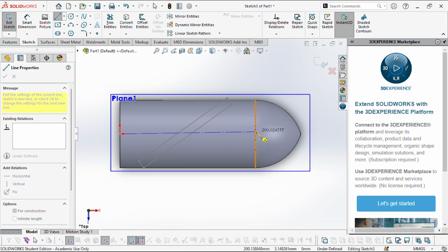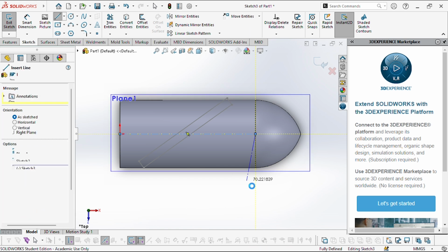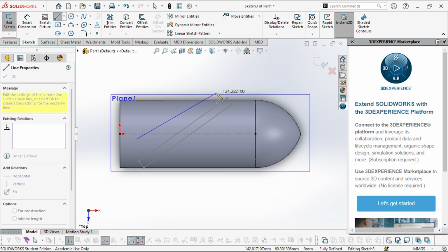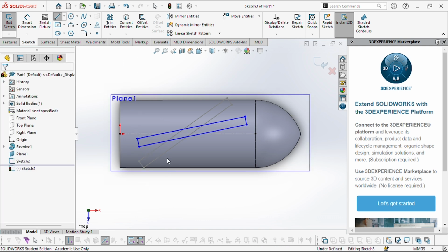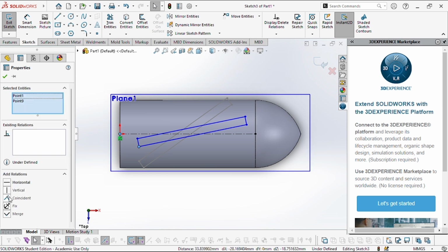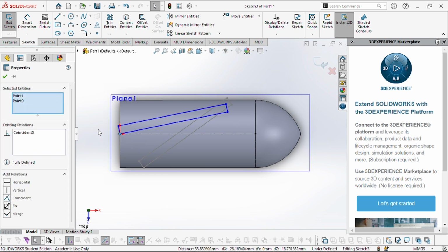Since the blade is going to be a twist, I would need to find an angle to draw the geometry of the blade that would best fit that twist, because it's going to be at an angle now. So I first went with just drawing the rectangle, then adding sketch relations to it. I added the relation, but I discovered that if I did that, there would be an edge protruding outside from the back.